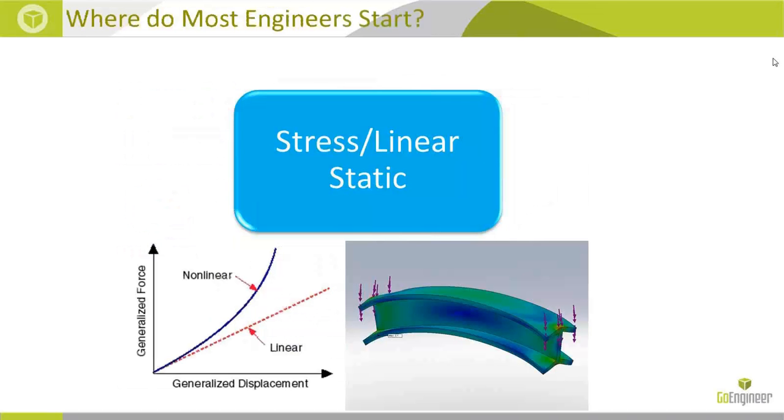So, in thinking about my experience as a design engineer, I question, okay, where do most design engineers start? Well, most of us start with, after we make a concept, after we answer the question of how we address new technology, advancement in technology, innovation. Where do we start? We start at linear static. We ask ourselves, is it going to break? We choose some material, and we understand that there's some generalized force versus some acceptable displacement that we're willing to accept before the product is no longer built with integrity.